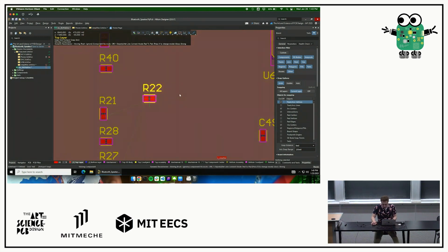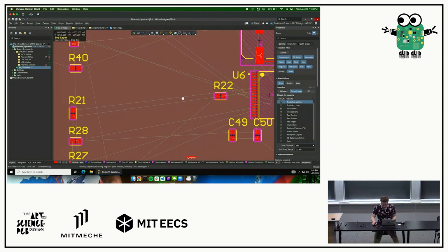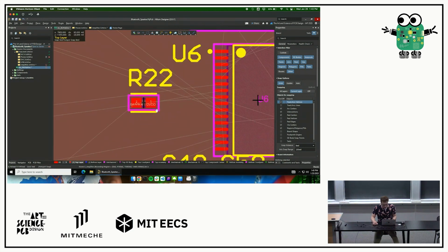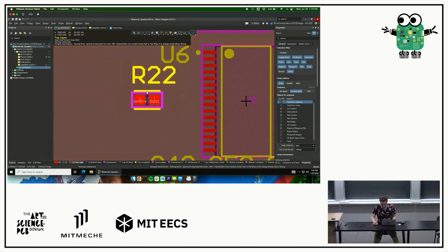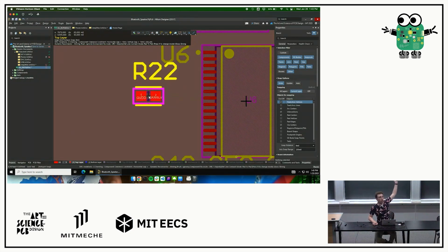If we take one like so and bring it over towards the side of the chip, when we go to move it, it'll tell us where this part should go. The projector might not be doing us many favors here, but can you see there's 2 little air wires that are trying to get this part over onto the side? If I wiggle it, do they seem a little more obvious? I promise they're there. You'll see them when you go to routing.